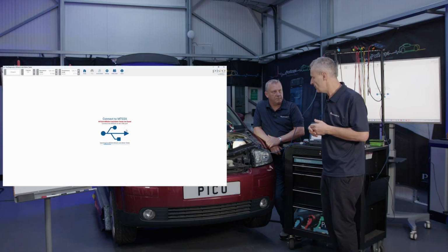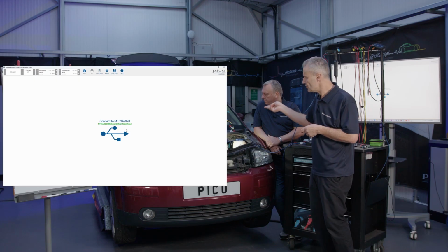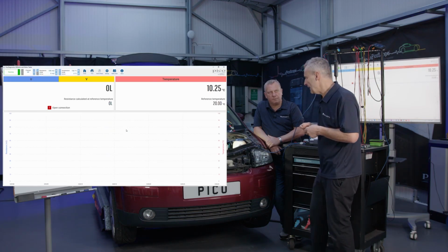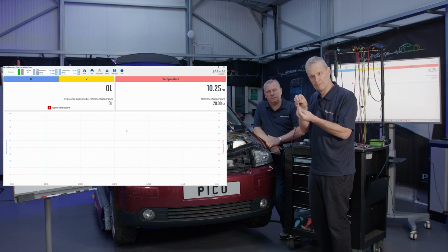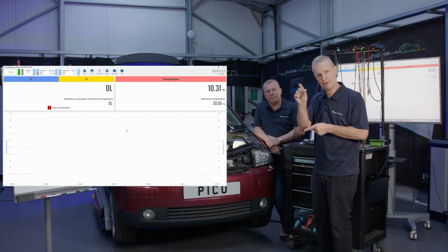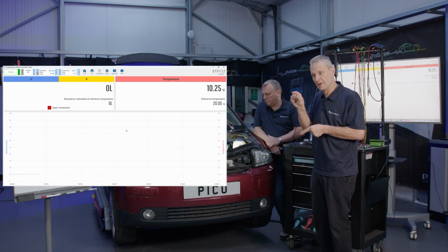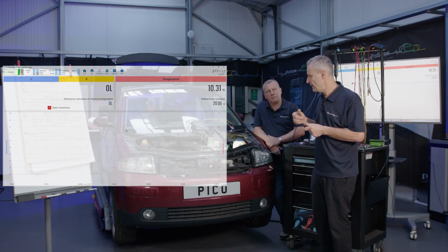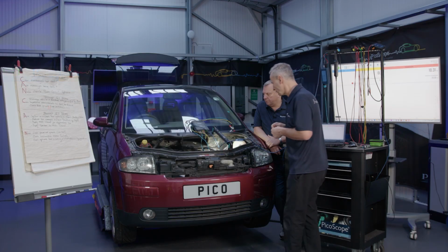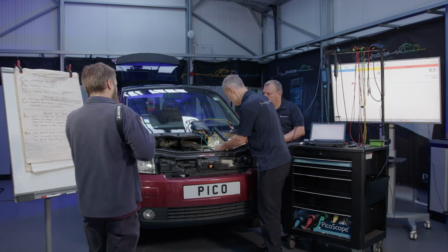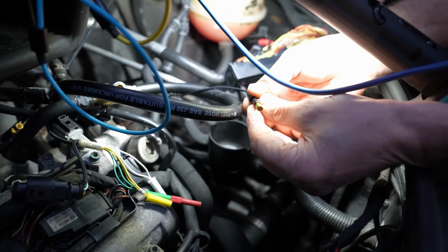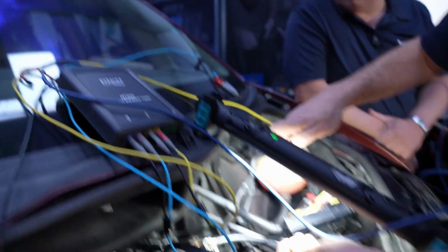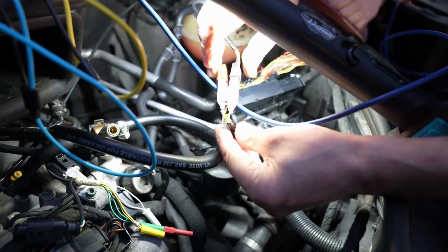This will be just testing 2 cables. You'll see here we got 2 probes. We do need to add to our clips a male connector so that we can actually open the jaws of the Kelvin clip so that they'll actually grip the clip. So Ben, if you come in, you'll be able to see this a bit closer. What I mean by that is, here's our breakout lead that goes into the ABS ECU earth cable. I'm going to push this into here. That's going to give us a great measurement point so that we can put the Kelvin clip onto there.